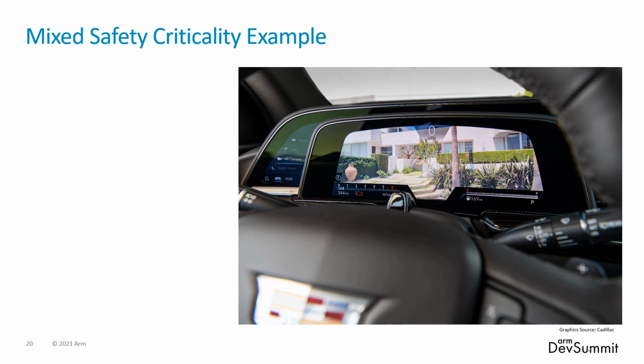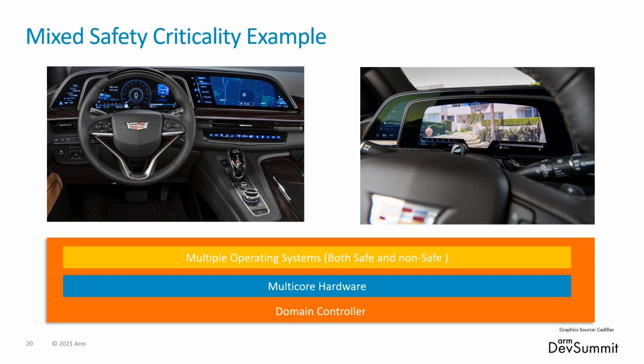So now on this cluster, you have the capability of running multiple operating systems on a single SoC, in both safe and non-safe partitions. Think about your radio. It's an annoyance that your radio goes out, but it doesn't really cause any harm, other than you're really disappointed that the station you listen to went out. Versus a functional safety function like a backup camera, where something could happen if that went out. So having both functional safety and non-functional safety on the same piece of hardware, in this case a single SoC, is becoming more and more apparent.